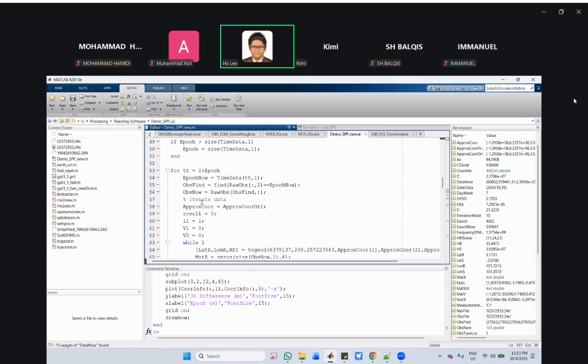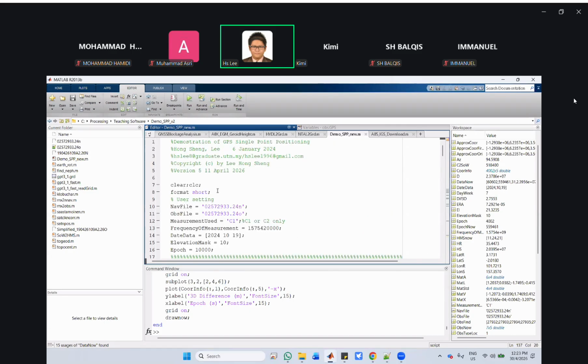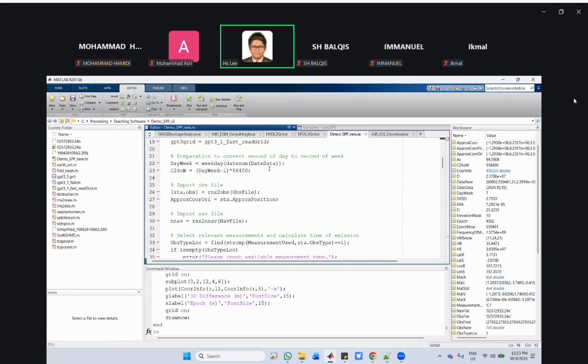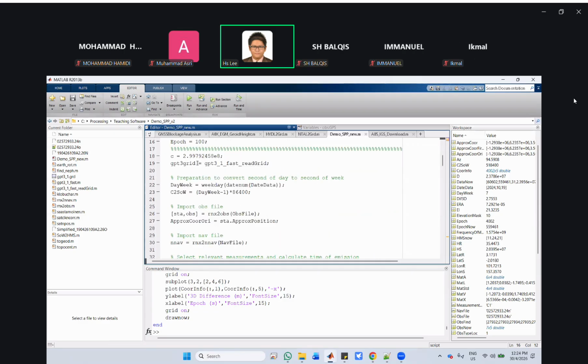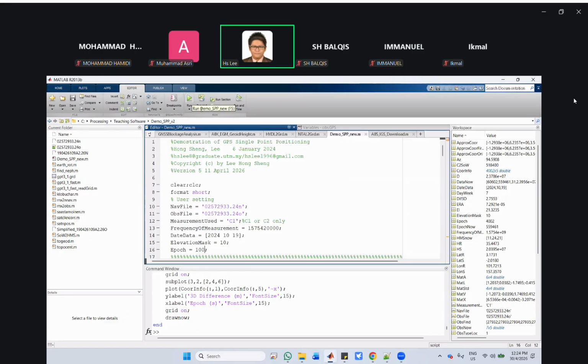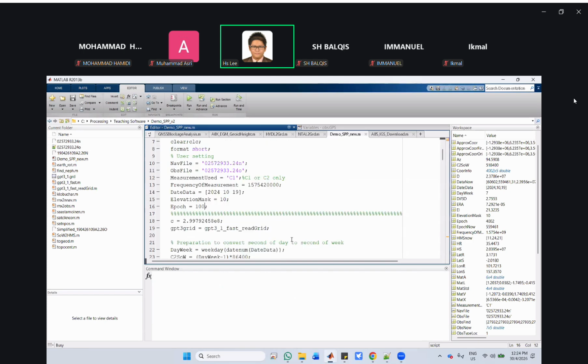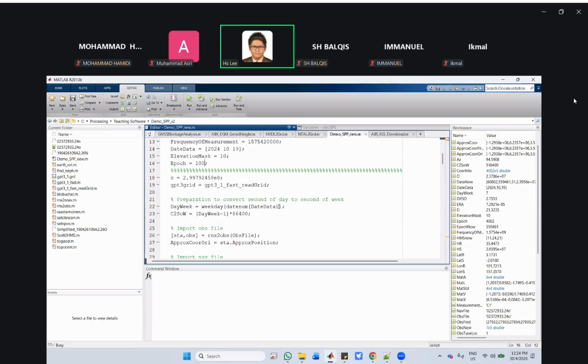In the default setting that I provided, we applied troposphere and ionosphere correction. What if these corrections do not apply? Okay, let me do one with all the corrections on first, but only with short epochs, so it doesn't run for too long.